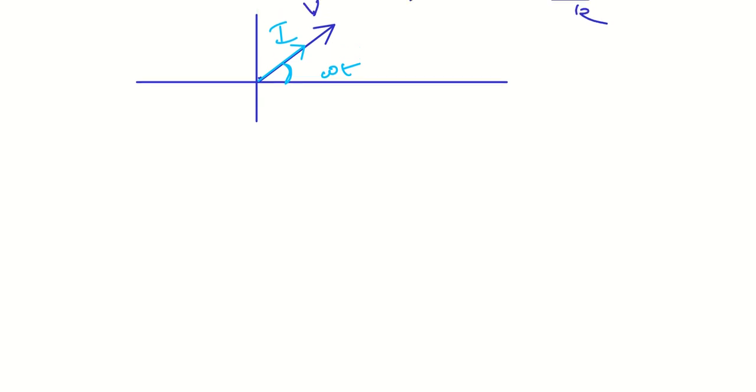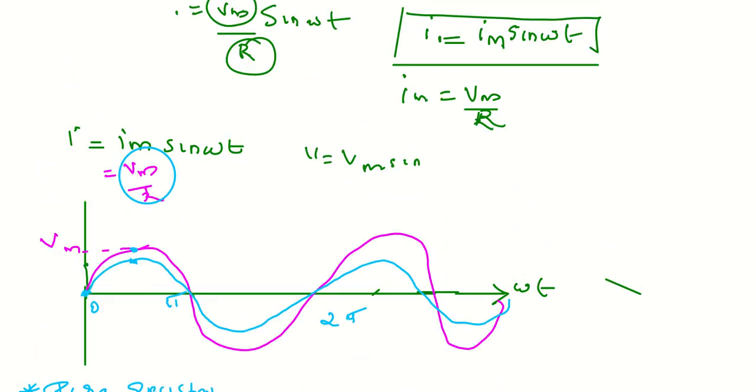The AC current varies sinusoidally and has corresponding positive and negative values during each cycle. Thus, the sum of instantaneous current values over one complete cycle is 0. So in this diagram, in each cycle there is a corresponding positive and negative value.